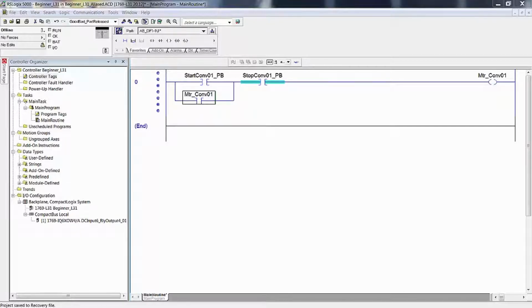What we mean by data scattering is, for troubleshooting purposes and programming purposes, it's good if all of the inputs associated with that conveyor, conveyor 1, are all on the same module in sequence and they're contiguous, meaning that there's no gaps in between them. That's what we mean by preventing data scattering. It is even better if you write the bulk of your program before I/O assignments, thus allowing the most logical, contiguous I/O assignment possible.